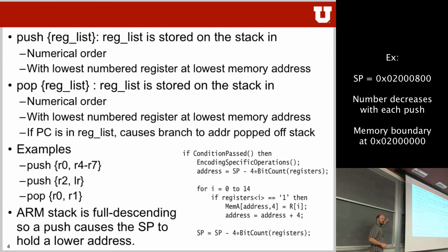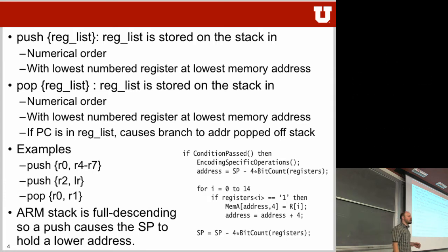And if you then execute another push, well, we went outside of the memory itself and we ran into a different memory area. Most likely you will get a memory hard fault and your program crashes. Right? So the size of your stack is the responsibility of the programmer. You have to think how much stack space you need, and that's where you put your stack pointer in the beginning.